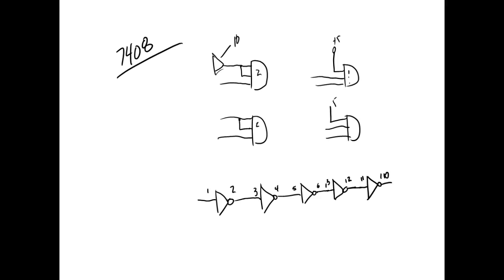Right. So 10 will go back to 9, and I'll hook my scope on 8 so we can look at that. So what I'll do on the scope is I'll look at the clock coming in, and then I'll look at the output, and we'll see which edge this thing detects. Now this is an AND gate, so we should expect it to find the rising edge, right? Or gates would find the what? The falling edge.